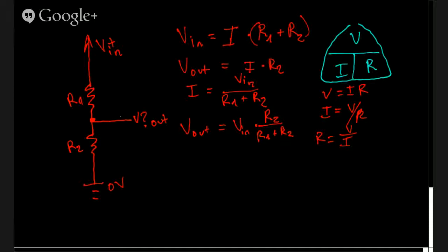Voltage comes in here. What kind of voltage will we have here given these two resistances? It's a pretty simple game of ratios. And so we can use voltage dividers to get a number of different voltages out, which will be important.